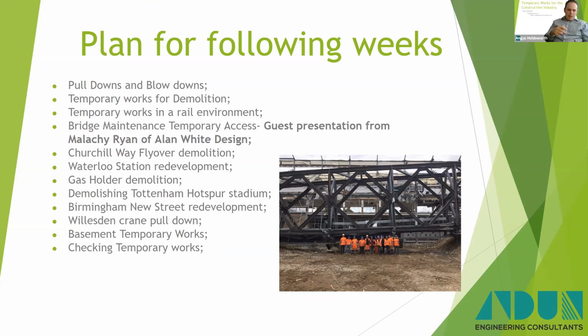So if you look at it from the scaffold designer's point of view, they're providing a scaffold that is there for dust and to prevent dust leaving the site and provide access to the structure if required. Now, there's no way you can design a scaffold that's going to stop a building collapsing, because the scaffold relies on the building for stability. So if the structure falls into the scaffold, it's only going to go one way. What they can do is limit the effect.